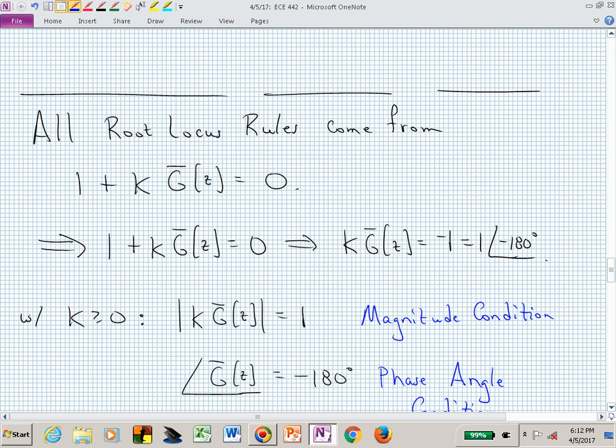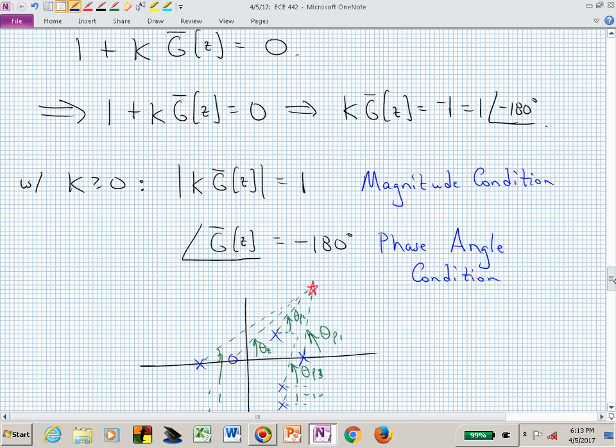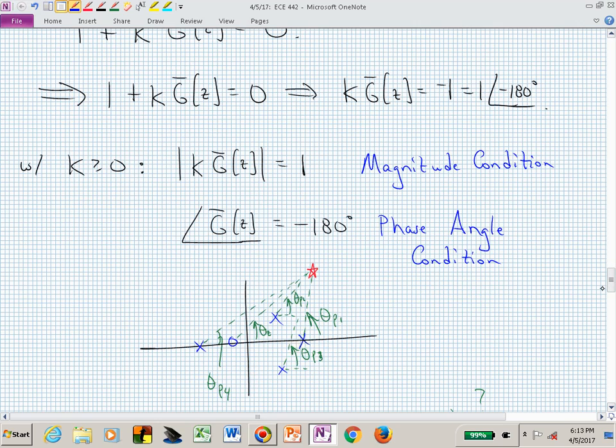And we'll use that to find k at different values of z. We also know that every point on the root locus has an angle or a phase. Algebraically, we take all the poles and zeros, their angles together, and they have to algebraically sum to minus 180 degrees. As an example, and hopefully here all of my poles and zeros are blue.